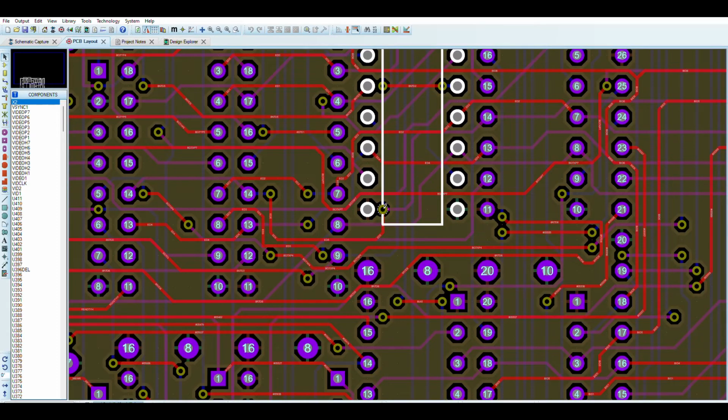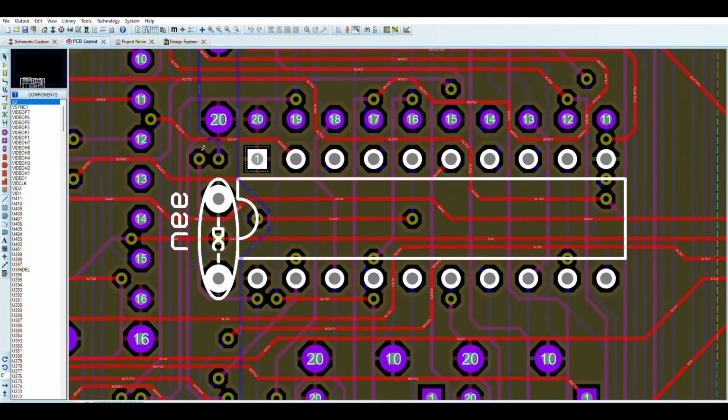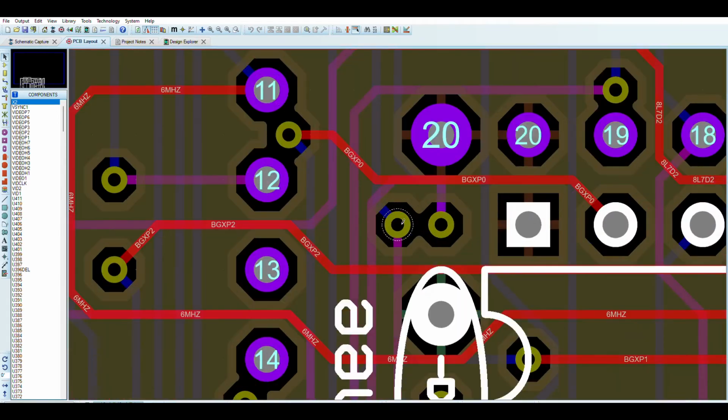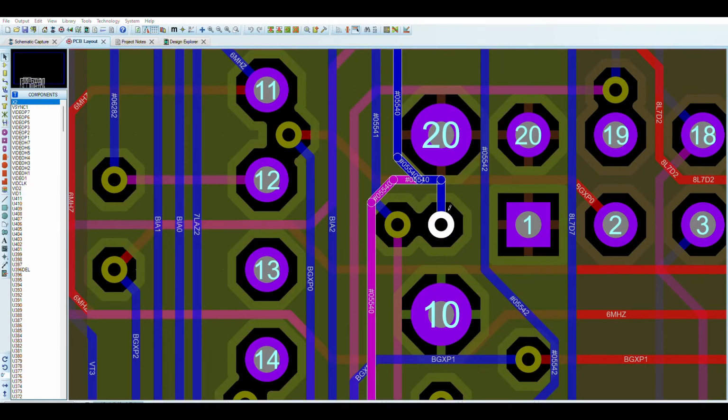The second issue is near pin 1 on U66. Near pin 1, it was actually a bridge across these 2 wires here. So these 2 wires here, there's this internal line here, and then there is this internal net here, and these 2 nets.